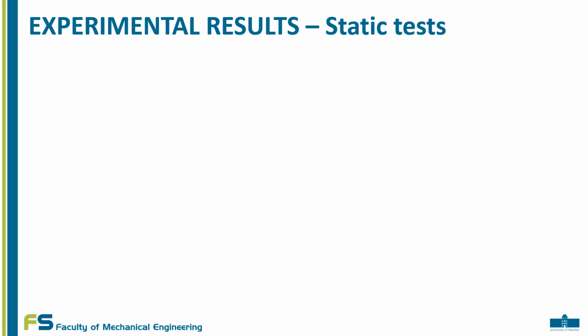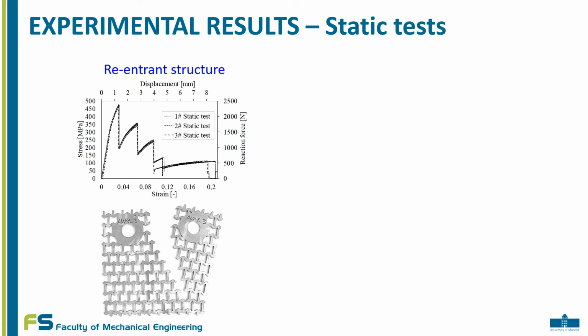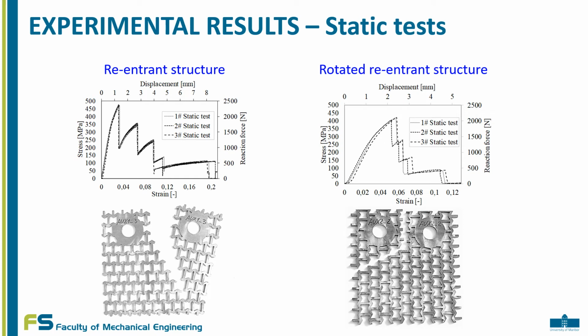Experimental results of the static tests. In this slide, the static curves for the re-entrant and rotated re-entrant auxetic structure are presented. Based on the static curves, we determined the loading levels for the low cycle fatigue tests of the analyzed auxetic structures. At the bottom of this slide, the fracture path of the analyzed structures under static loading is presented.